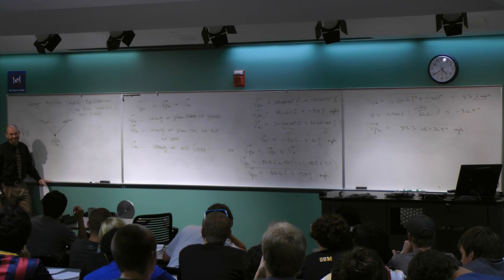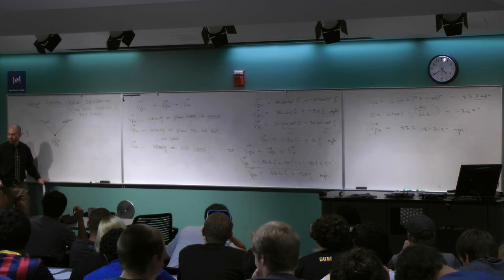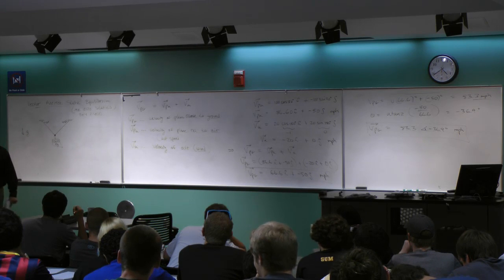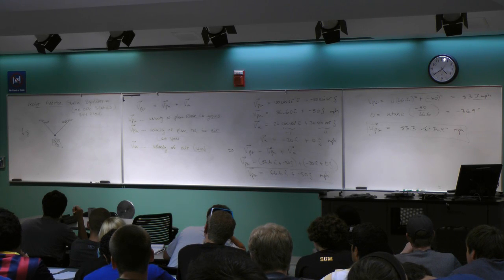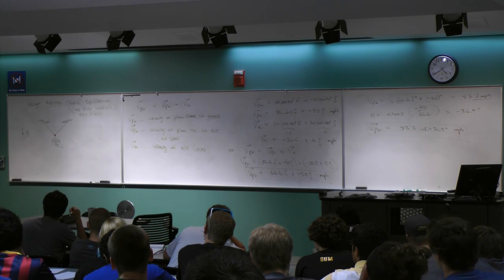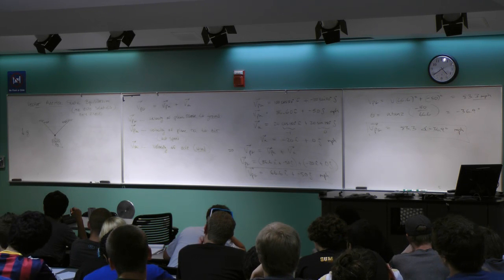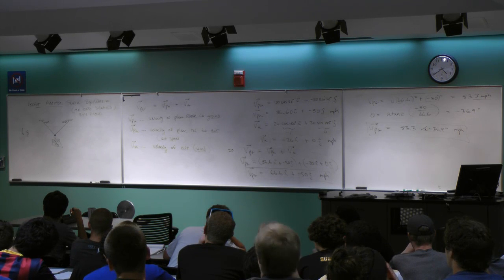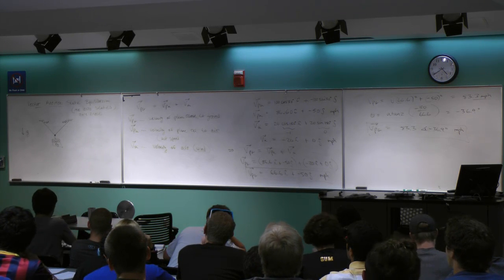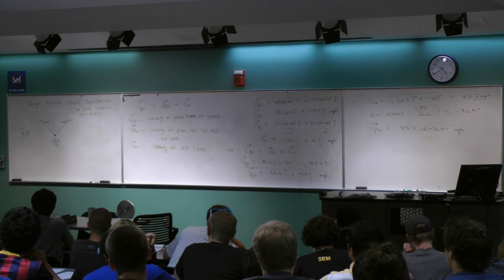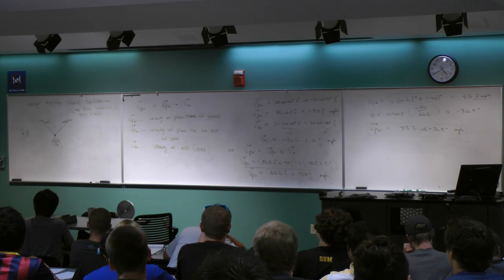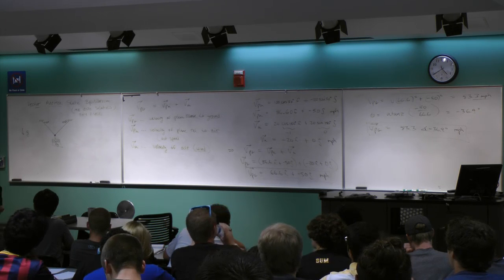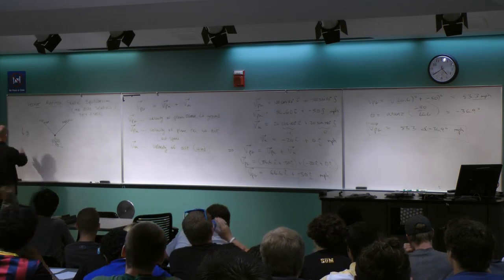That one's weight. Okay, so you got to keep your wits about you, like what's the language we're using here? If we say 1,000 pounds and we're doing a statics problem, we're talking about pounds of force. That's weight. I'd have to back out the mass. When we're in English, the tradition is to talk directly in terms of weights as forces. When you're in SI, weight isn't a base unit of anything. The base unit is mass, period. You report something that has weight by indicating the mass, and that means you always have to multiply by g.